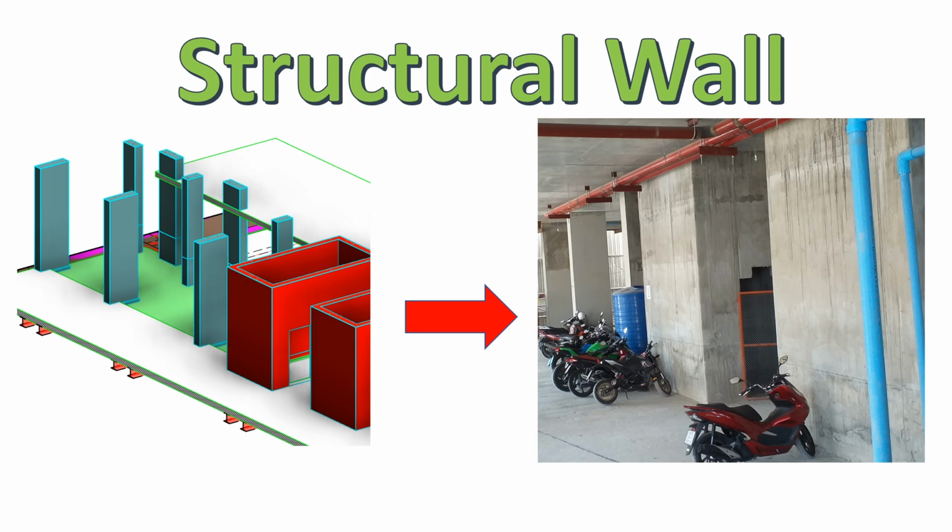In case you have the vertical steel plate welded to structural steel member to form some kind of combined structural steel wall, you still can apply the basics of structural wall modeling explained in this video. Because the finite element process for both concrete and structural steel is the same for the linear elastic analysis. Only material properties are different.